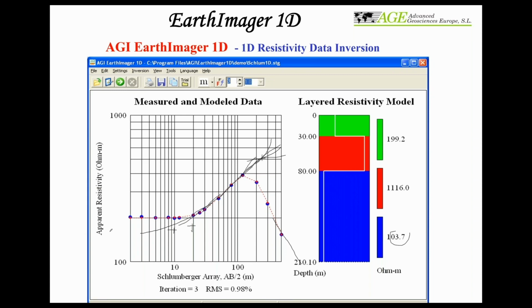your measurement. It gives high contact resistance, and sometimes you get a high contact resistance of 30,000, 50,000 ohms. That means I cannot inject good current there. Maybe I'm injecting less than 20 milliamps, 10 milliamps, 2 milliamps. In that case, it's very weak, so that will result in noisy data. So I want to avoid that.